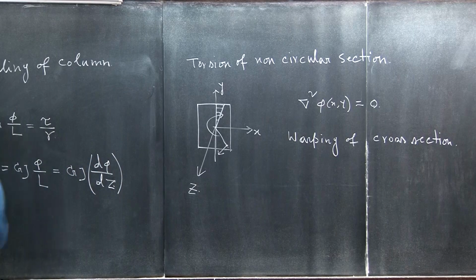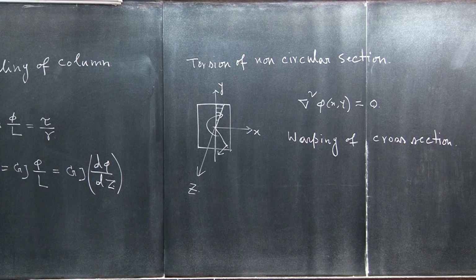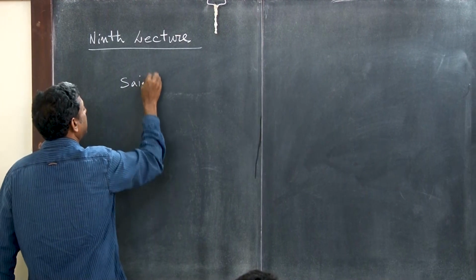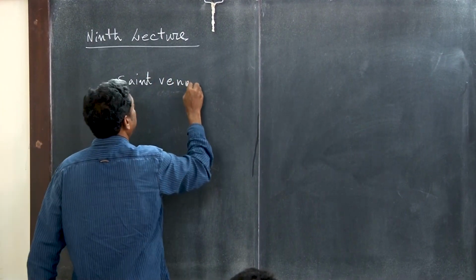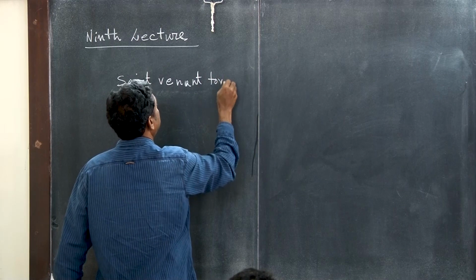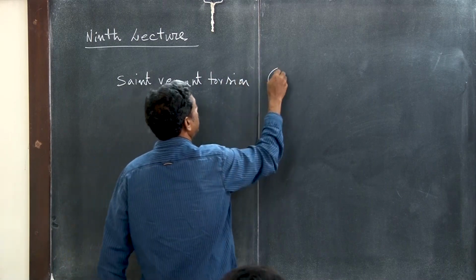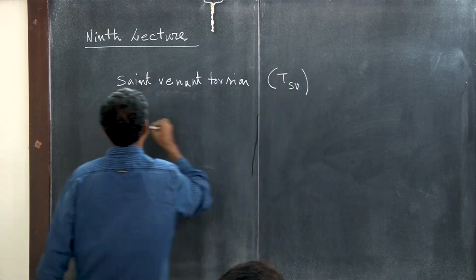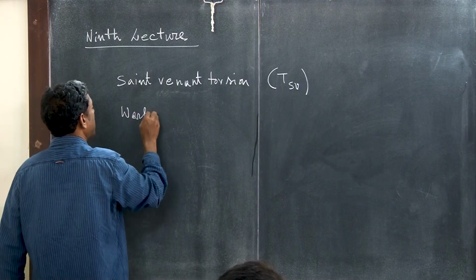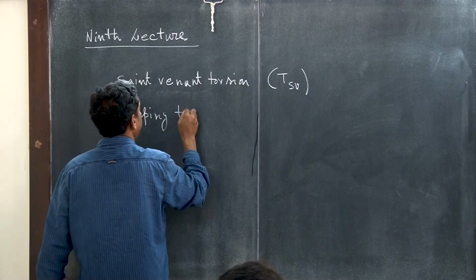Please note that this warping induces additional stresses if it is prevented. What we have learned is that there will be two components, Saint-Venant torsion and warping torsion.